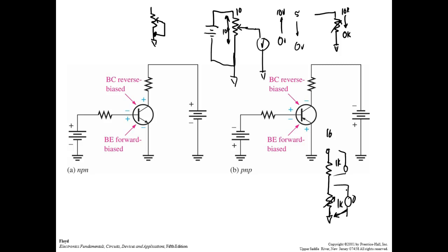So across the pot, the current flow doesn't change. It's always the same. Well, what we're doing with our transistor is acting like a rheostat. So if I run it like this, we have to put a resistor in series with it, because if I adjust it all the way down to 0, something's going to burn up because I have a short circuit. So when we run a transistor like this, we'll always have this resistor we call a collector resistor. And so we're varying the voltage drop across this guy, and when the voltage drop across here goes down, the voltage drop across here is going up, because Kirchhoff's law says the sums of the voltage drops.